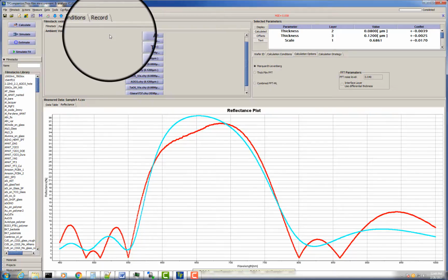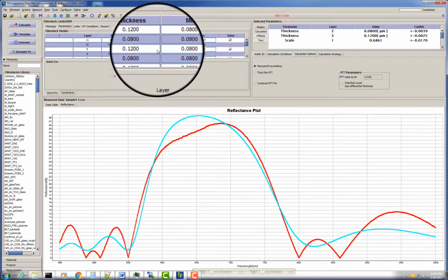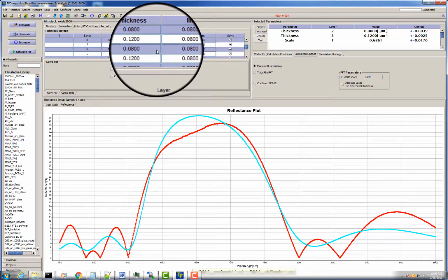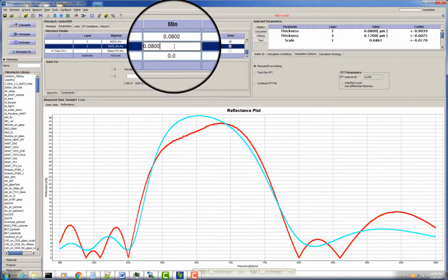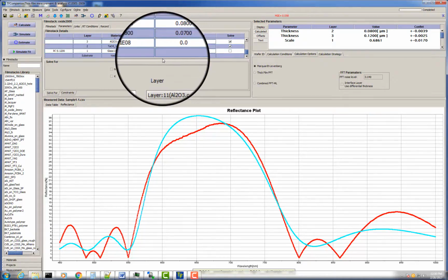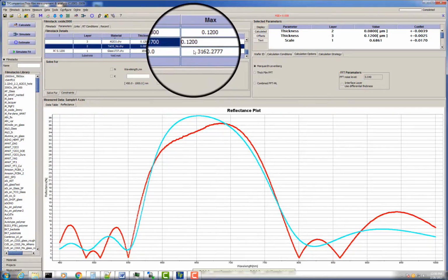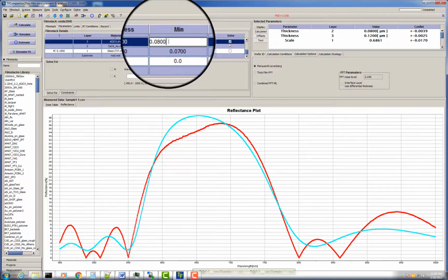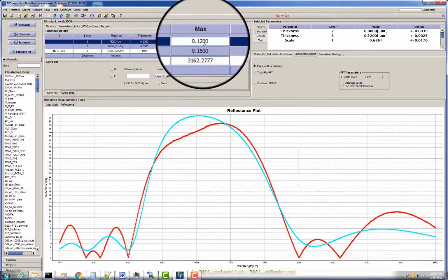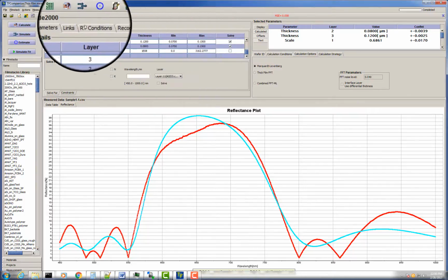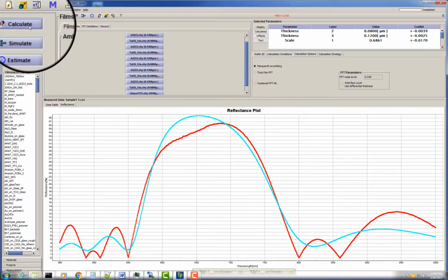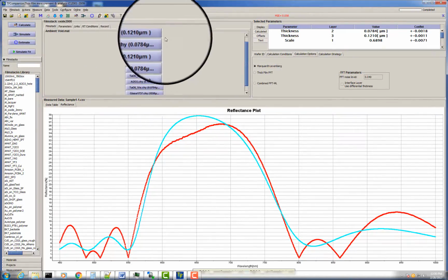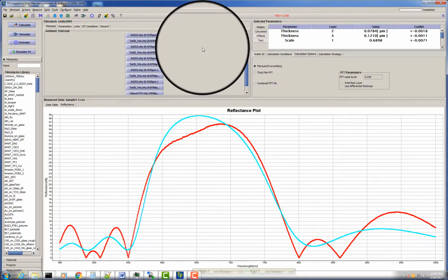So our next step is we need to allow thicknesses to float. We need to basically unlink the layers. Oh wait, we have a little problem here. We put constraints, but the constraints are too tight. So we need to make the range wider so that thicknesses can be adjusted more accurately. Otherwise, they're just bumping into limits, and it's not good. So we'll just change it, make it a little bit wider in 2 layers, and it will propagate to the other linked layers. And see.